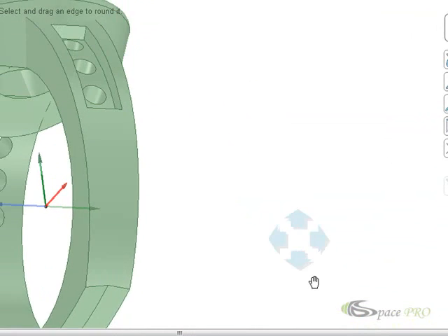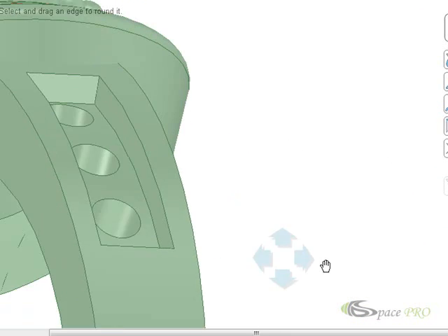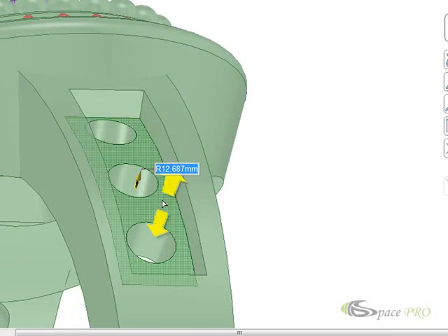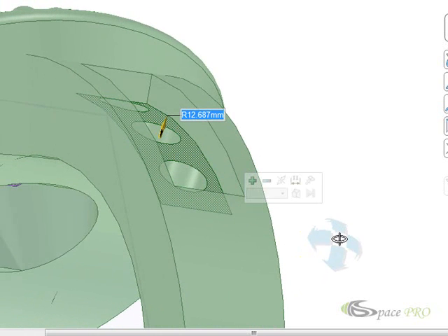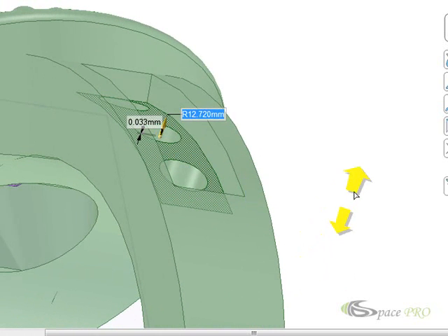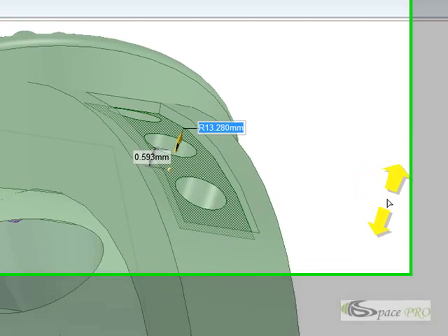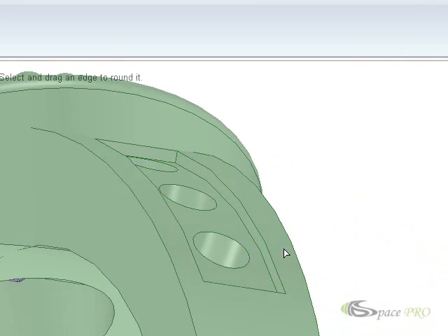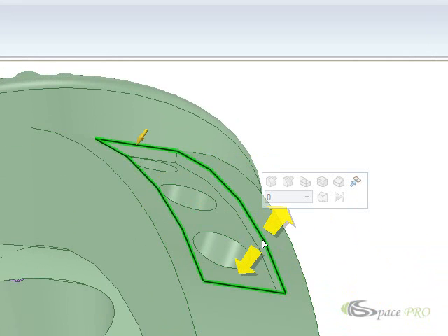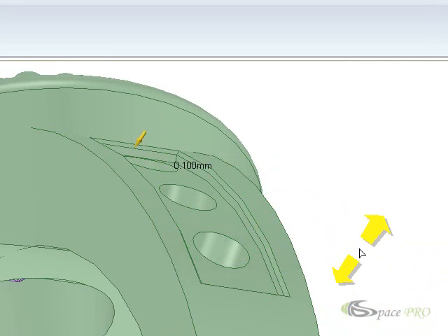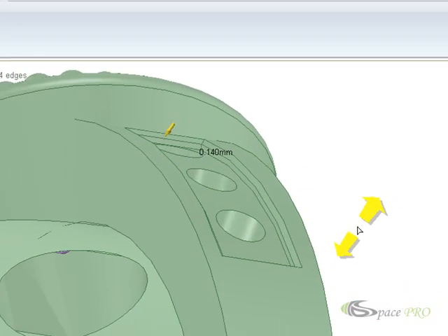After we create the ring, we're going to change the way that we did the channel, and we're going to take this channel part and create a pavé. We can move the surface up to how high you need it, and as you see we go with the numbers. I can double click on these four corners and chamfer the side for pavé.